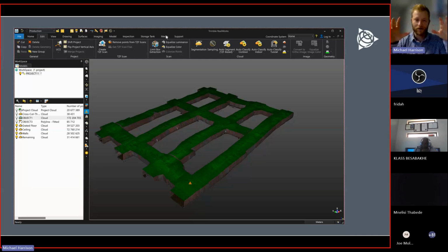So there is potentially some cleaning up you have to do. If I look at this point cloud now, I can see that my ceiling is fine. My walls are okay, especially if I'm going to be meshing this. There's small gaps, but generally I'm going to subsample my point cloud down before I mesh anyway. For the floor, if there's gaps like that, you can trim out some of the remaining point cloud that is floor and add it back into the graded floor layer. It's not always necessary, as I'll show you in this example coming up next.